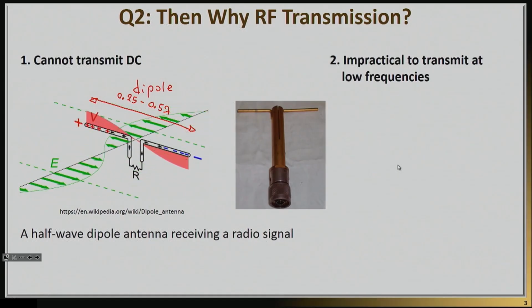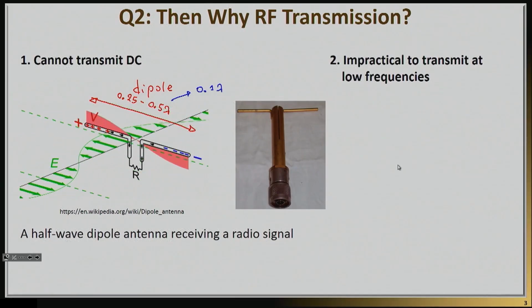And you know, if you are pretty good in antenna design and you're willing to make a little bit of a compromise in terms of efficiency and in terms of bandwidth, maybe you can push this down to perhaps 0.1 wavelength. So less than that actually becomes really highly problematic, and there are niche applications where we do that, but let's just pick this as a rule of thumb. So if you actually do try to transmit at, let's say, 1 gigahertz, then you will find out that the length of your antenna has to be, let's say, 0.1 times the wavelength.